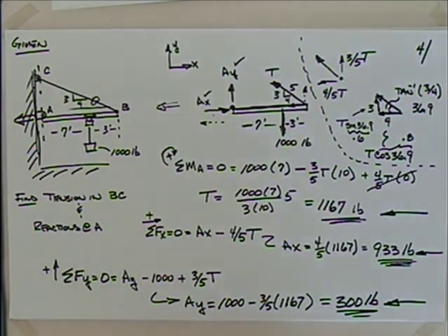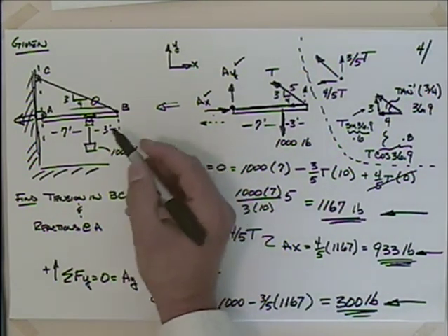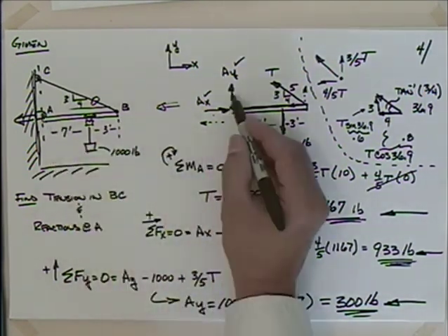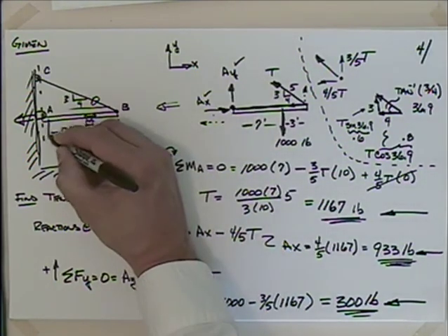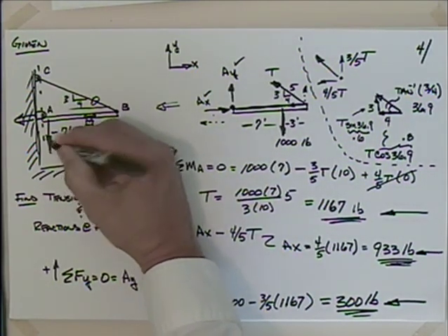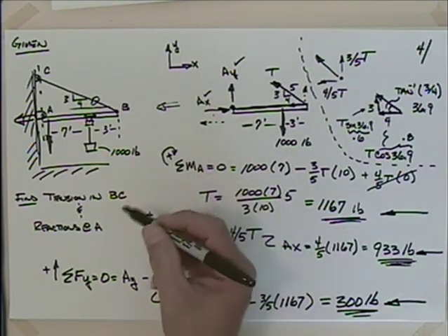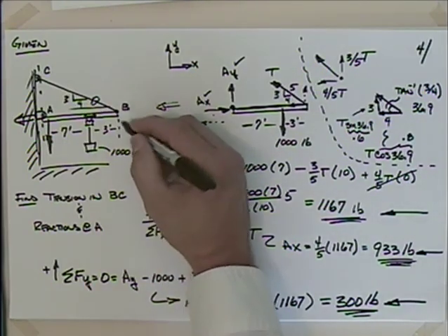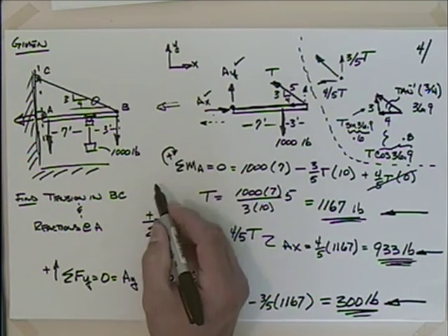Well, speaking of design, is this an exhaustive study of this situation? Well, not really, because where's the largest load in terms of Ay going to be? Well, that's when the load's right over here, right? So maybe we'd have to analyze that situation. And when's the largest load for the tension in this cable? Well, that's probably when the load's way out there, right?